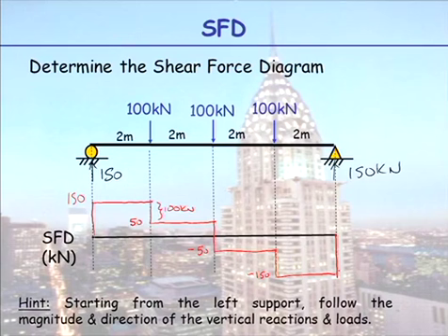So what does that mean? If I were to cut the beam here and asked you what the shear force was there, you would look at the diagram and say the value of the shear force is plus 50. What is plus? Plus is where the two shear forces cause an anti-clockwise rotation. If I, however, were then to cut the beam further along the beam, so that relates to that location.